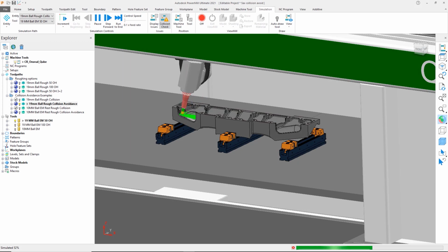When rough machining, we can encounter areas in the part geometry, such as deep cavities or steep walls, where the tool has the potential to interfere with the part, requiring tool configurations that are less than optimum or where additional programming time is needed to properly machine these areas.